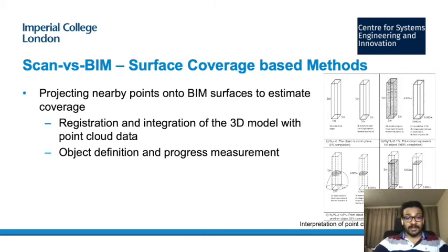This approach depends heavily on domain-specific knowledge injection and resulting heuristics. If points can only be observed on some sides of the object, the main BIM representation is scaled down along the main direction of construction. Since this process is performed iteratively, the number of necessary scaling transformations determines the percentage of that particular element present in the sensed point cloud.